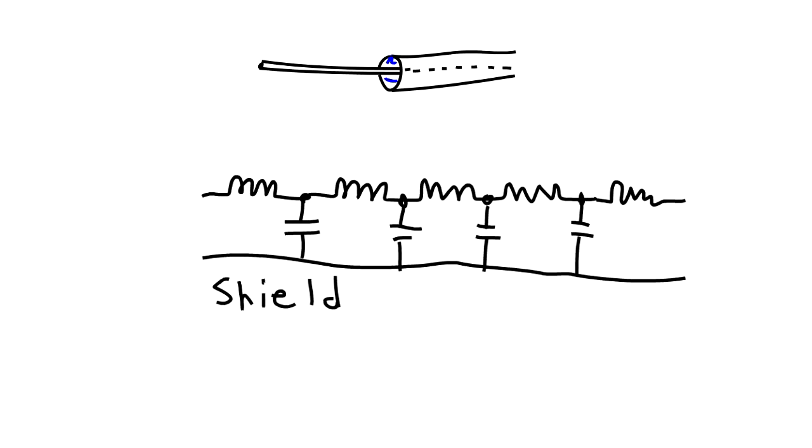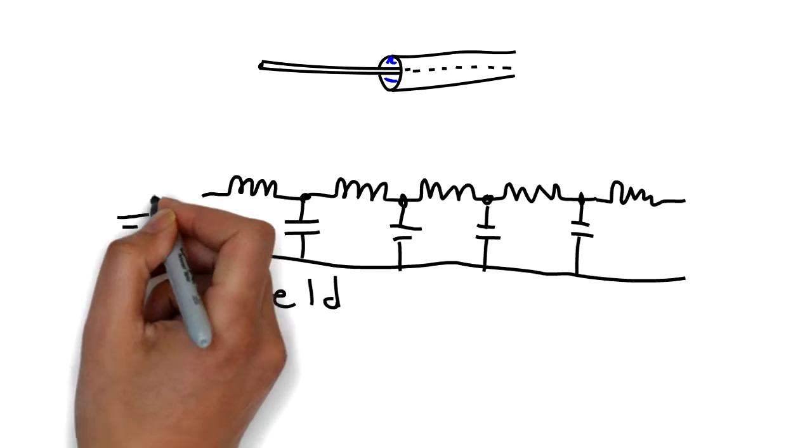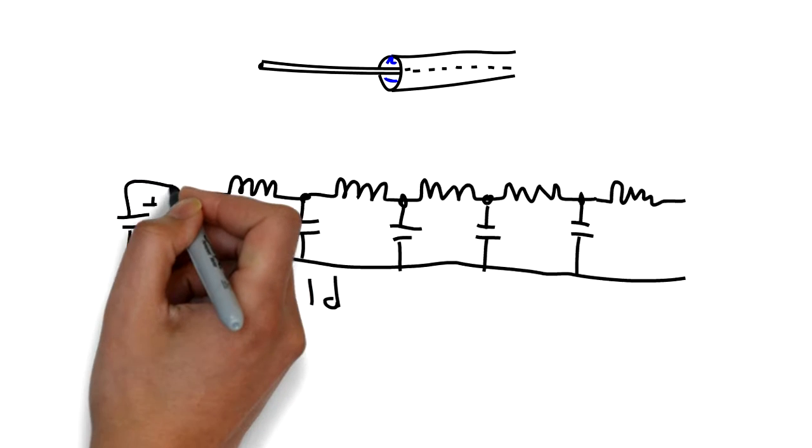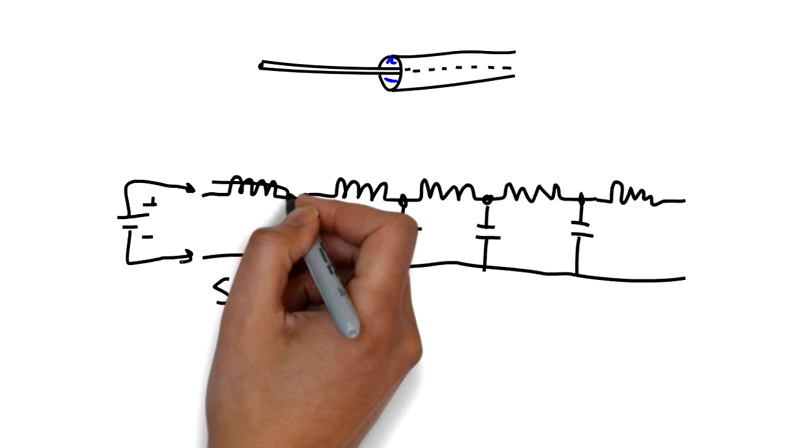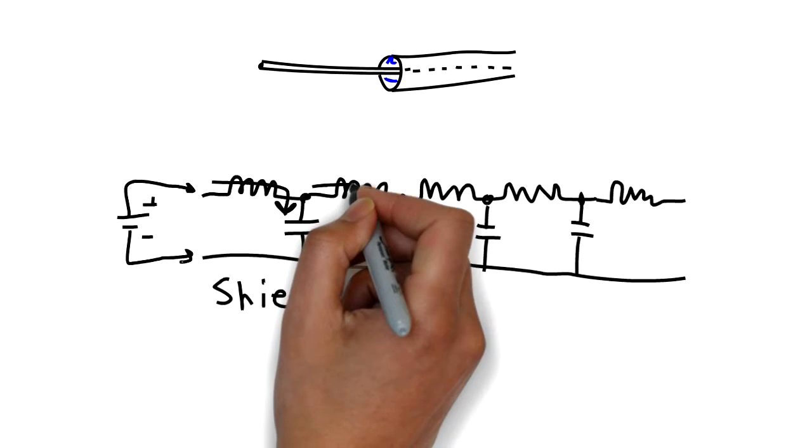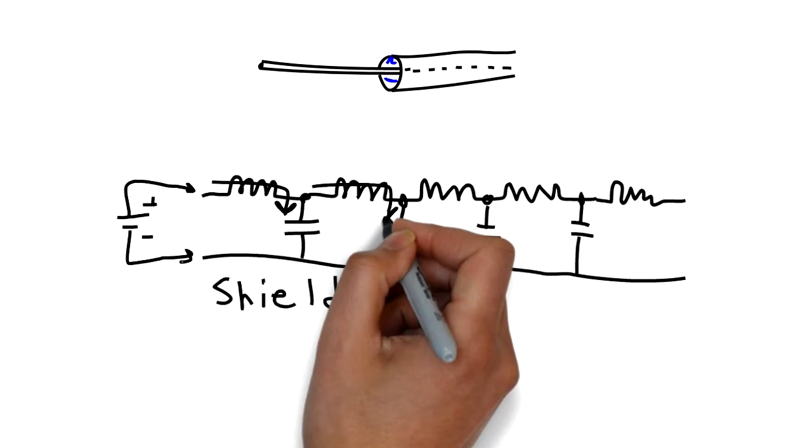Can we use this transmission line model to understand how signals can be sent long distances at much higher speeds than a conventional circuit topology we saw before? You bet. Let's go back to the whiteboard for a startup product design understanding of transmission line complexities. Say we take our transmission line and momentarily apply a voltage source. Current will ramp through the inductor and start charging the capacitance of the line. This will continue along the elements of the line.